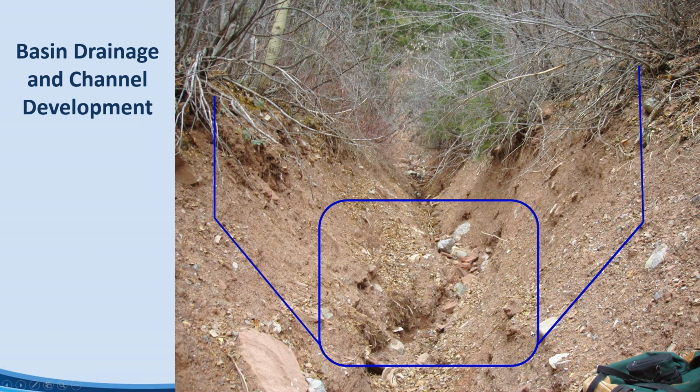First of all, there's this curvaceous rectangle or square here. Let's say that this is the potential flow area that would evolve as the flow came down the channel. That means there's going to be some erosion, and typically if it's a mudflow, it tends to make this channel more U-shaped, a little bit like what I've drawn here. But you should also understand where the sediment supply is coming from. It may involve some scour through this material down to bedrock, and if there is some scour, in this case, you have these rather steep banks that exist in this triangular shaped channel, and this channel is going to become more trapezoidal shaped or U-shaped. You'll see that if you walked back up into this watershed after the event occurred, it might look something like these outer bands here.